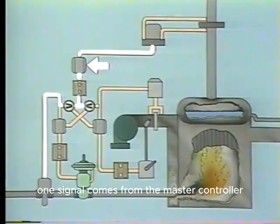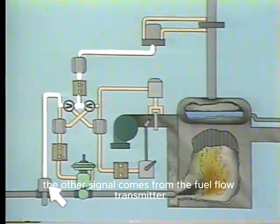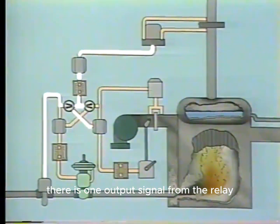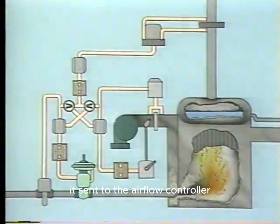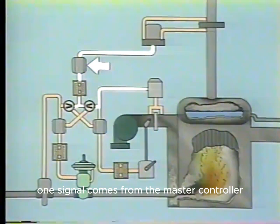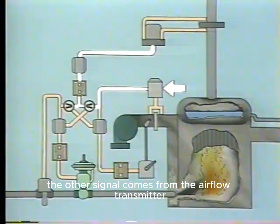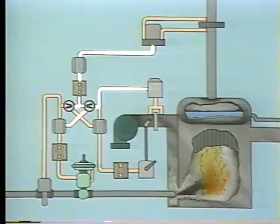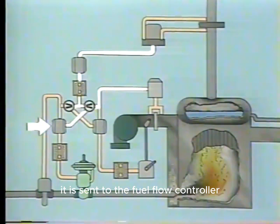This relay receives two signals. One signal comes from the master controller through this hand auto transfer station. The other signal comes from the fuel flow transmitter. There is one output signal from the relay. It's sent to the airflow controller. This relay also receives two signals. One signal comes from the master controller through this hand auto transfer station. The other signal comes from the airflow transmitter. There is also one output from this relay. It is sent to the fuel flow controller.